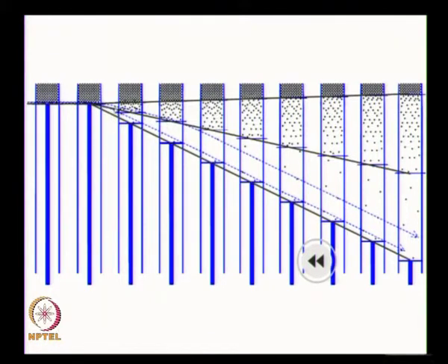We saw that a similar thing is happening in the compression wave, the oblique shock also, but I cannot show you what is happening inside a shock there. Here it is a big region, I can show it to you very nicely. In the other case, the area between the streamlines will be very large before and after the oblique shock. If the streamlines turn, they will be much closer to each other. I cannot show you anything more than that. In here I can show that the stream tube is expanding during the expansion fan, after that it is staying constant cross section between them.